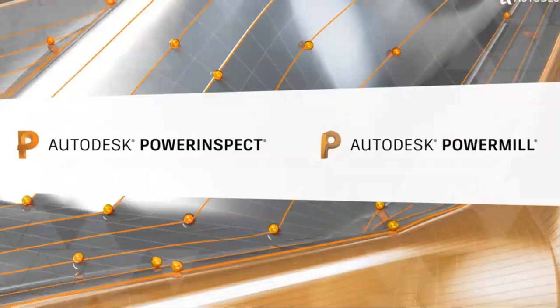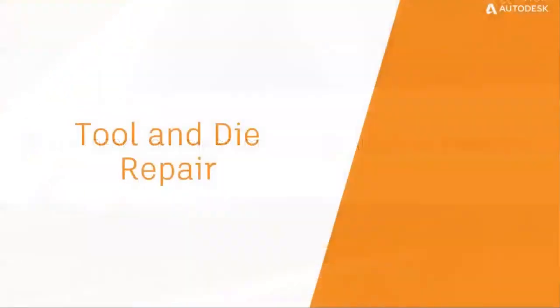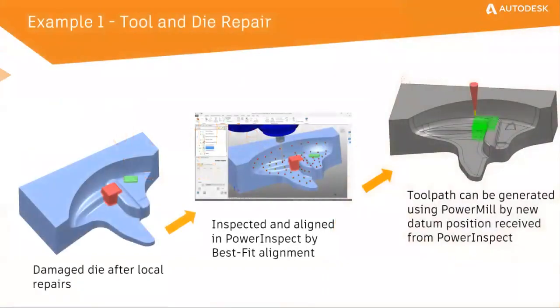And through PowerInspect and PowerMill, you can do this joint activity. Through PowerInspect, you can generate the datum or delta, and it can be transferred to PowerMill for creation of the toolpath. So I have a small example of how adaptive software fixturing works. In this case, if you see, this die tool has been damaged. The red colour area is the area on which the customer deposits the material. This is the extra material.